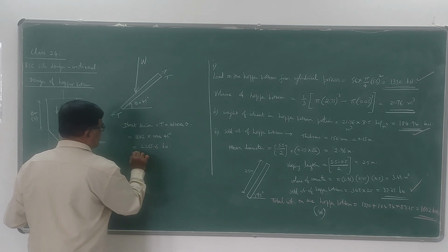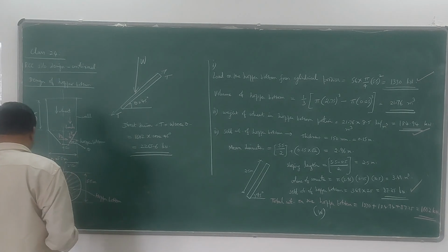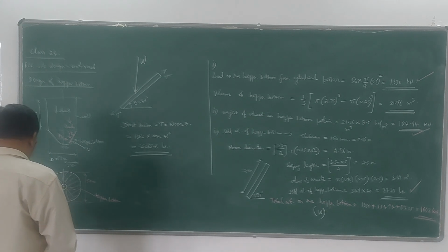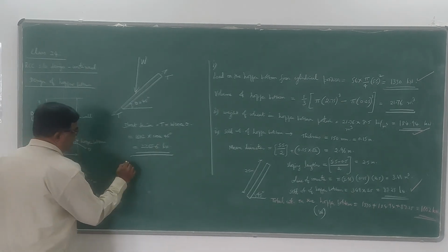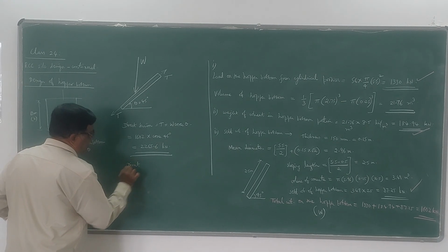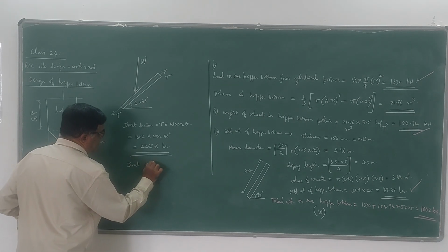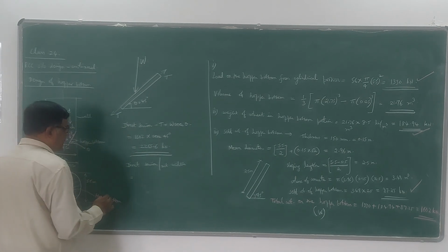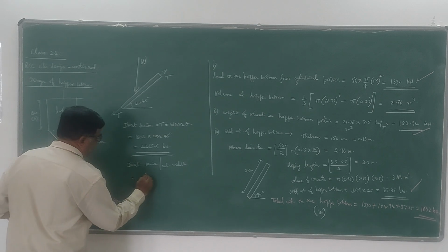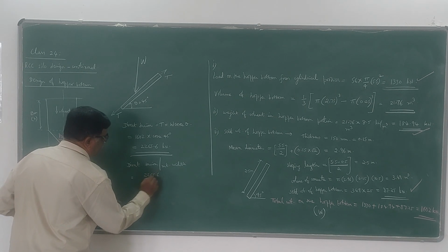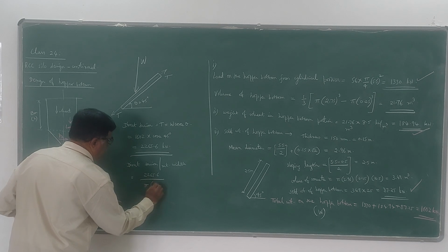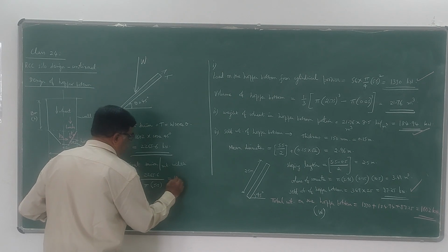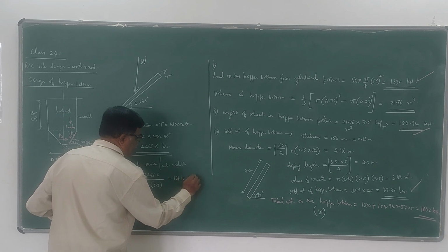So this is the direct tension force for which that hopper bottom has to be designed. Now direct tension per meter width we have to calculate, because reinforcement we have to calculate per meter width. Direct tension per meter width is 2265.6 divided by circumference, pi into d, so pi into 5.5, which comes out to be 131.1 kilonewton per meter.